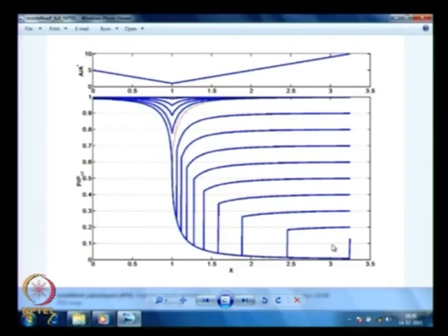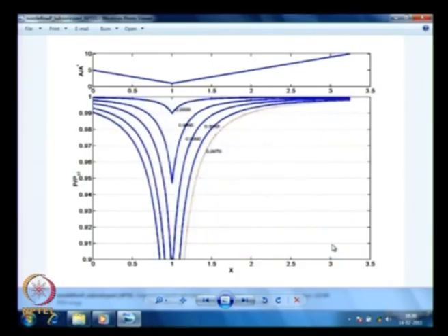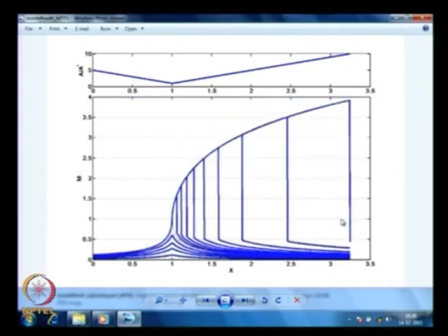Now we will go to the next plot. We had this Mach number discussion anyway. This is the Mach number plot. Okay. Now whatever she was talking about is actually true, right? The strength of the shock is actually related to how subsonic can it take the flow, if you think about it that way. Actually let us explain this again, the same nozzle plot above, A by A star versus distance along x axis, and here I am plotting Mach number at every location versus x axis.